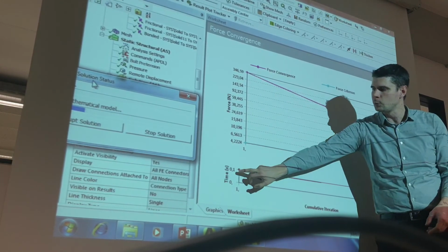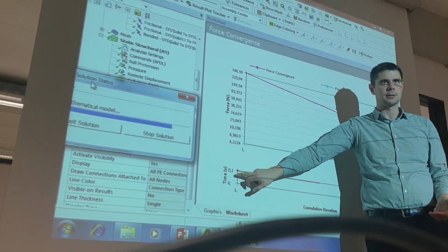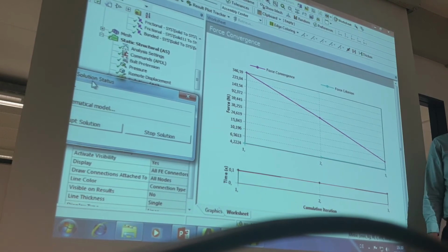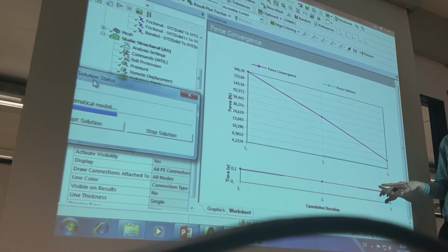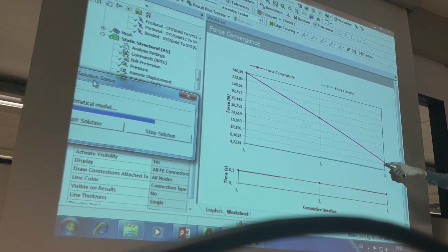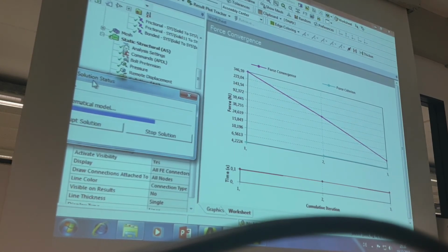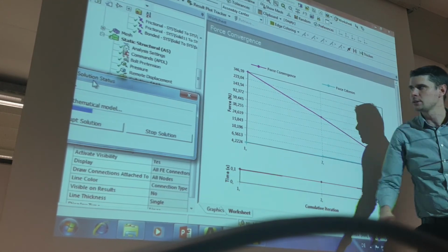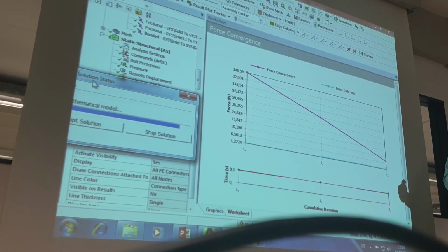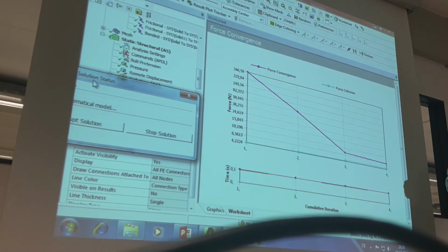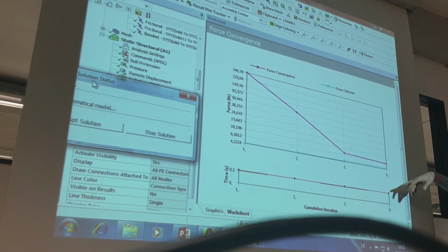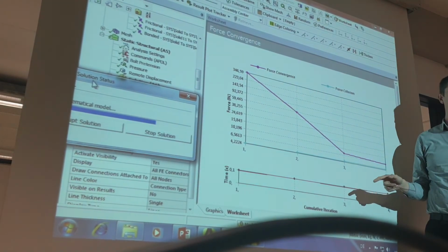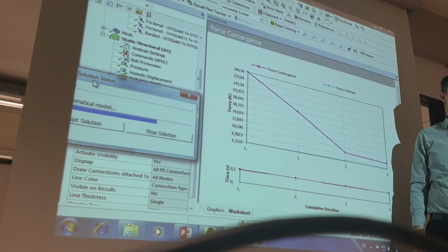First the program tries to calculate 0.1 second. 0.1 seconds means 800 Newton out of 8,000 Newton. And you see iteration number 3. Every iteration is a system of linear equations. The program tried to calculate first this situation, this one system of nonlinear equations. To calculate a system of nonlinear equations, we need to calculate many systems of linear equations. And we see we are near. The problem will be if our error grows up. It means the time step was too big, for example.